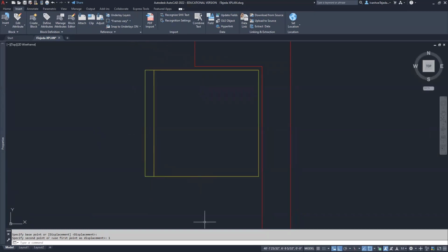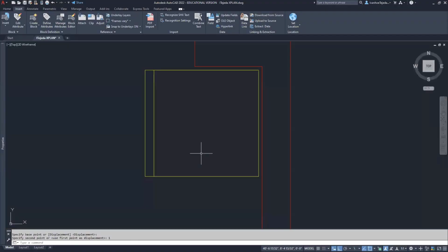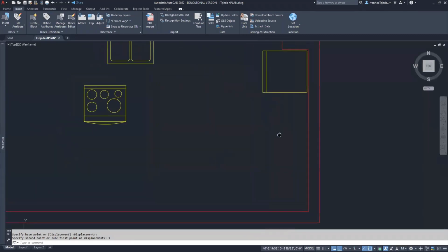Now what I'd like to do is go ahead and put in the countertops. What we do is we draw them at a default depth of 2 feet. We know that they're slightly wider than that or deeper than that, but that's just what we typically use in these architectural drawings. Drawing it at 2 foot depth is going to be fine. So I'll go back to my drawing. I'm going to zoom out like this.